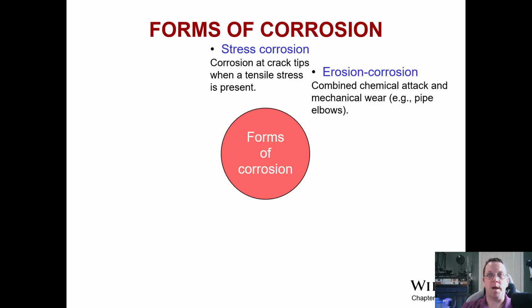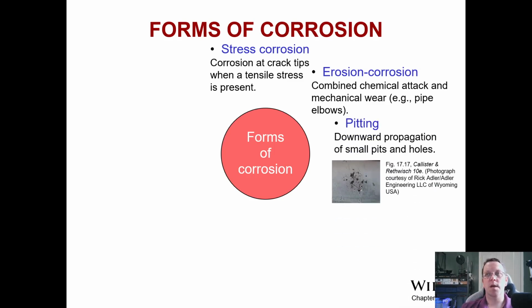Every time there's impacts, there's chances of knocking some of that material off the surface, and you have erosion over the course of time just because of probabilistic statistical mechanics and chemical attack on the surface. Over the course of enough time, that creates the conditions for significant erosion, even with erosion resistant materials.